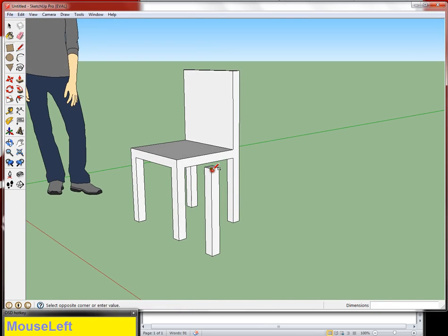So I'm going to grab the rectangle tool again and build a rectangle here that's 2 inches by 2 inches. And as you notice, since it's a square, I got that dashed diagonal line here, and I know that that's a square. Also, my dimensions read 2 inches by 2 inches, so I didn't have to type a measurement to get a perfect measurement there.